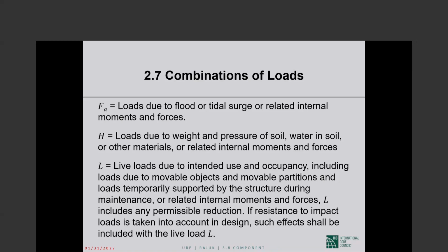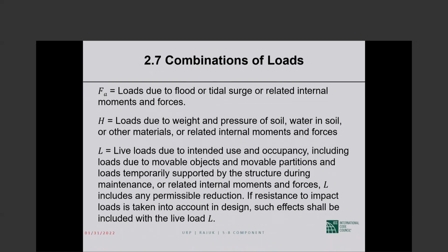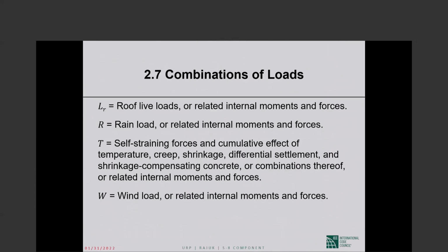L without a subscript is floor live load. L sub R is roof live load. Capital R is rain load. T is a difficult term. I think T stands for temperature effects, but it is the best way to describe T. It is the effects of restrained volume changes.